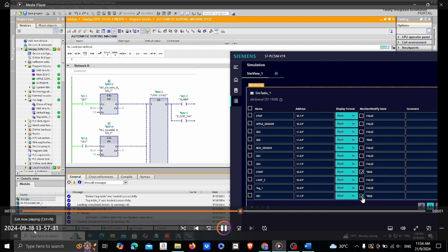The pulse for the shift register is activated by the sensor SE4 that generates one pulse per rotation. If sensor 5 detects any box, then conveyor motor B must be stopped. One Hz flashing light at the alarm lamp. The buzzer also will sound with a 2 Hz pulse tone until the reset button is pressed. So the boxes will be counted according to their height. If any of the boxes reaches the quantity of 12, the operation will stop until the reset button is pressed. The operation will continue without pressing the start button.